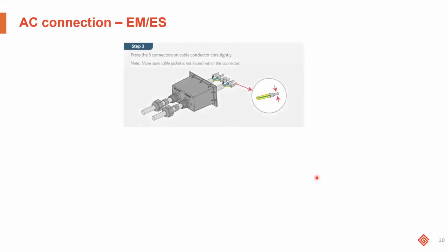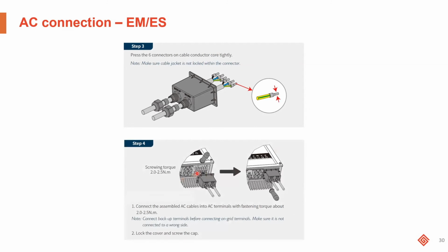I would also recommend that you crimp on some bootlace ferrules, as we say in English. I'm not sure what you call them in Dutch, but this also helps with the termination into the terminal of the battery inverter or the hybrid inverter that we have here. So these types of connections aren't new to you. I'm sure you do it every day, so I don't really have to spend too much time on this.